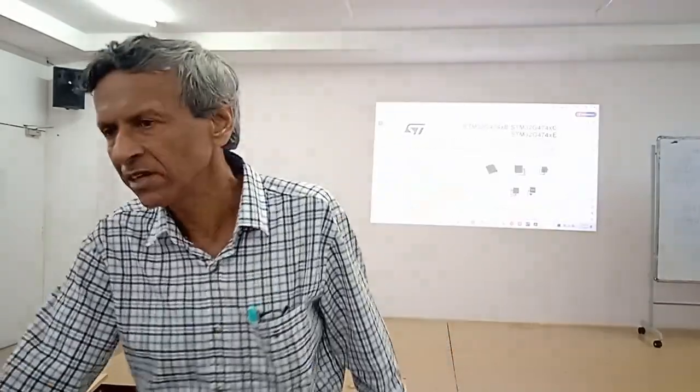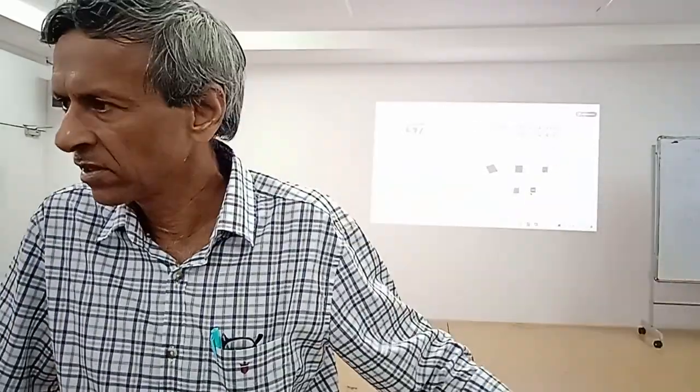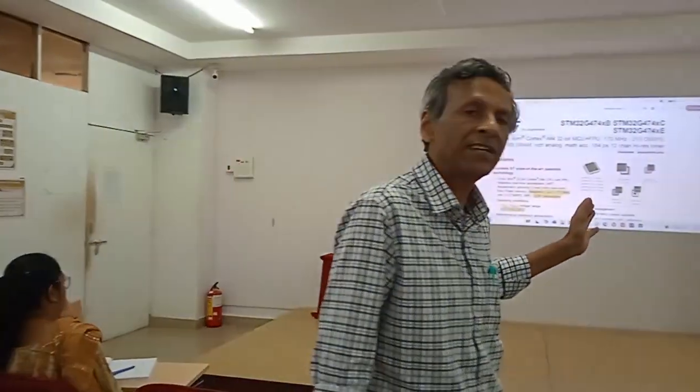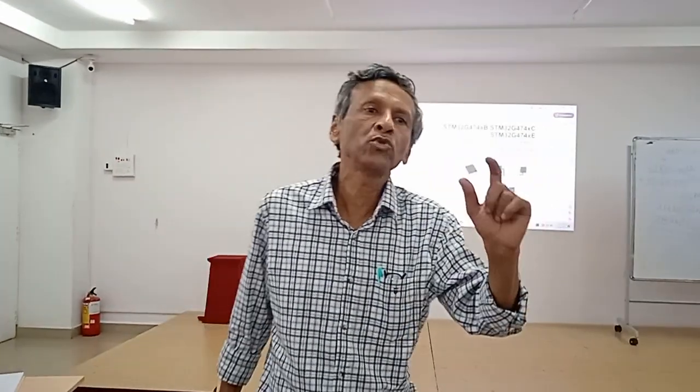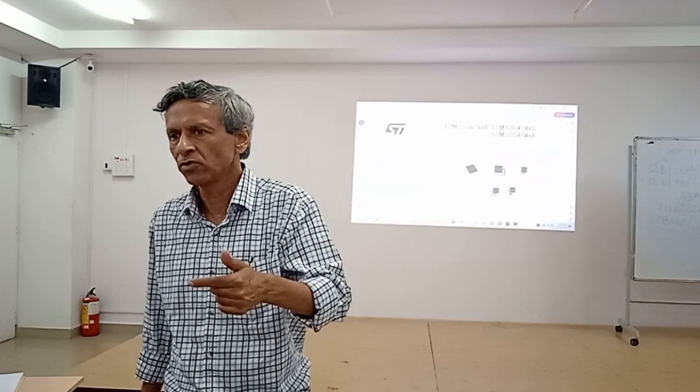Somehow they are achieving it. In fact, it is not zero wait state. There are some wait states, but they are not 3. Then a table is given for that. But for now, we have to believe them that it works at around 210 million instructions per second, or 213, zero wait state execution from flash memory at highest 170 megahertz. Any question? So this is the first specification suggested by ST, and it has got two cores, CPU plus FPU, two cores.